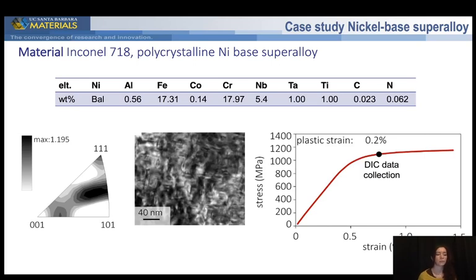Before starting, one should keep in mind that the longest and most intense slip bands are the ones that produce the highest extrusion on the sample surface. These ones are the most critical ones in terms of fatigue crack nucleation. So during fatigue, slip bands will form during the very first cycle, so we really need to understand where and why they form, and we can do that with a simple monotonic test.